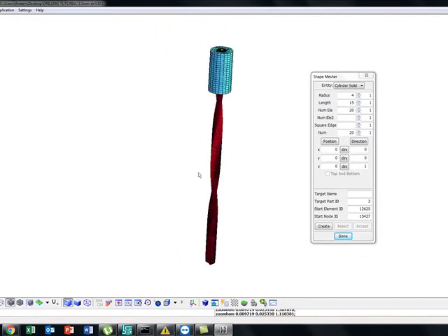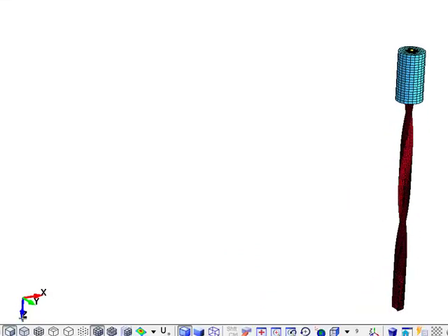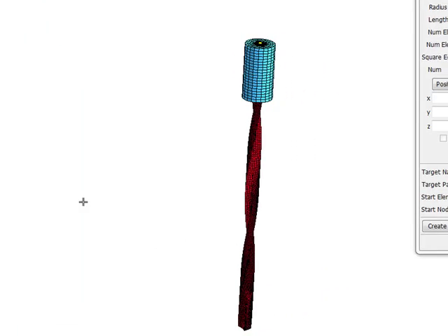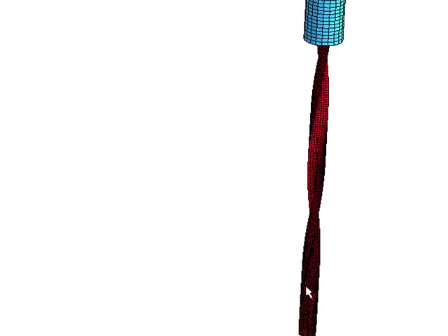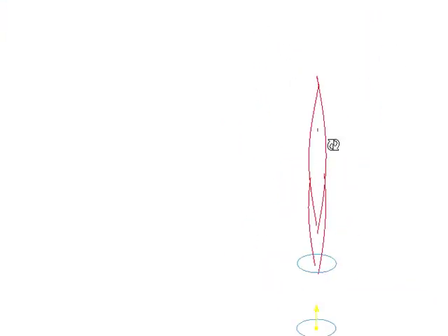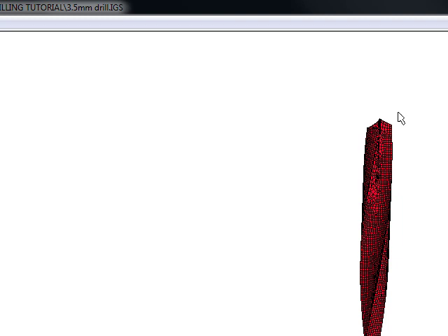So now what do you see? This is your specimen, and it is actually clashing with your drilling bit. If you look here, you have XYZ. So this whole thing is actually upside down. You click on control and hold the mouse button, and you can flip it. So actually the real thing is like this: the specimen is down and the drilling bit, the tool, is up, but now it is flipped upside down. So what we're gonna do now is flip this tool. You see the head is up, we want it to be down, so we need to flip it.